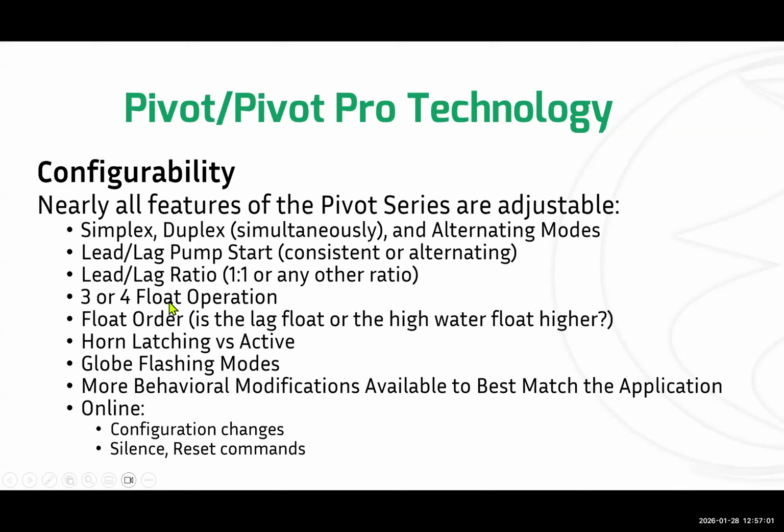You can set it to 3 or 4 float operation. I'm going to stop here for a second and comment on this. We say this in all of our literature. It's on the first page of our manual, in the quick start guide, and in the quick reference guides. But we recommend for most applications, and this doesn't matter if you have a simplex or duplex panel, only using 3 floats. There's one exception to that, which I'll touch on.